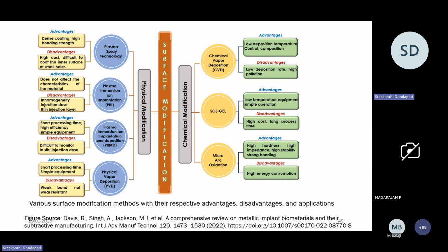The main advantage when you go for conversion coatings is the peel off. You will have very good adhesion strength of the coating. When you go for deposition type of coatings like PVD, CVD, over a period of time you will see that the coating has faded off or damaged. But with these conversion coating processes, the adhesion is so high because its own surface has got converted. So there is no question of poor adhesion. It will have very good adhesion strength.